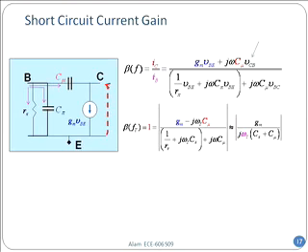Now, do you see the expression I have from the top. I'm just taking the absolute value. Now, given normal transistors, the C mu term on the top, the capacitance term on the top, is generally small. There's no a priori reason, but people have historically seen that. So, you drop that term. So, you only keep gm. And similarly, 1 over R pi, which is forward biased diode current, that's small. So, you drop that one also. So, you have that particular frequency.